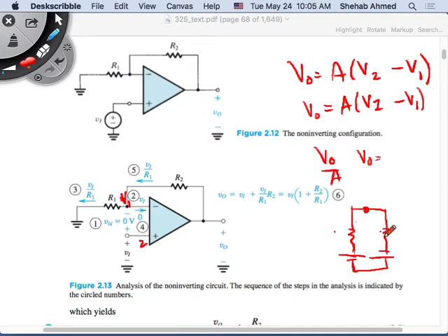But if I make this resistor very small, I need to make this voltage source smaller, because if I make this small, there is less resistance in the circuit, so more current will flow, then a larger voltage drop, which opposes this source. So I can make this large, because remember my gain was 1 plus R2 over R1. So maybe I made R2 large.